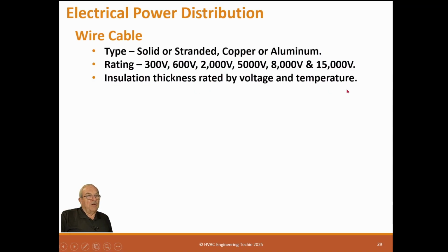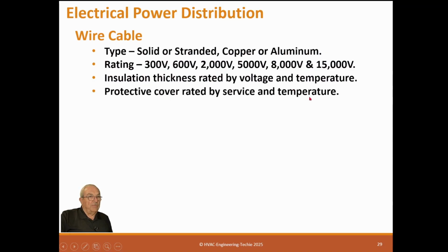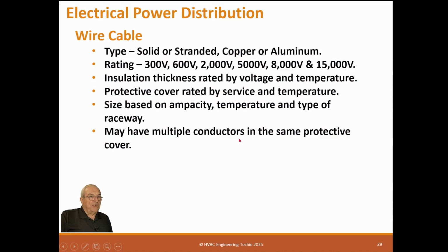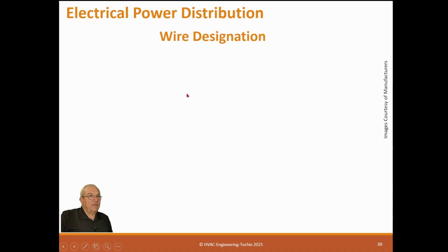Insulation thickness rated by voltage and temperature, protective cover rated by surface and temperature, size based on ampacity, temperature, and type of raceway, and length, of course. May have multiple conductors in the same protective cover.